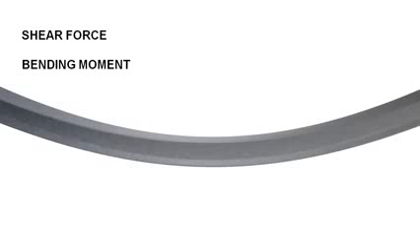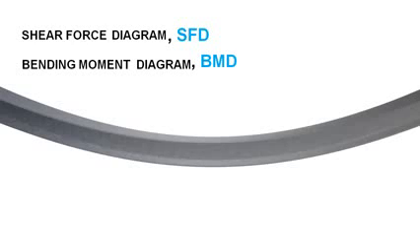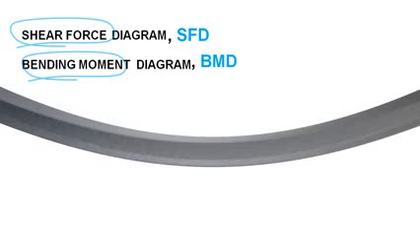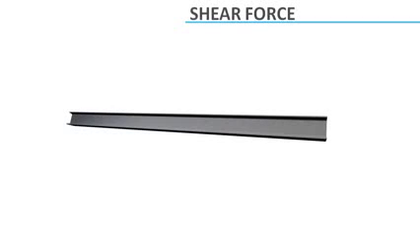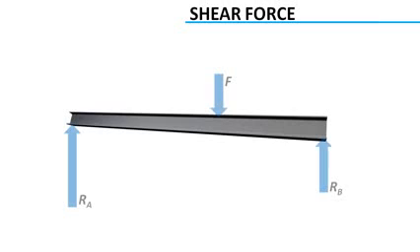The interesting thing is that you can draw shear force and bending moment distribution along any beam, by understanding what exactly is shear force and bending moment. First, shear force. Shear force is the resistance created in beam cross-sections, in order to balance transverse external load acting